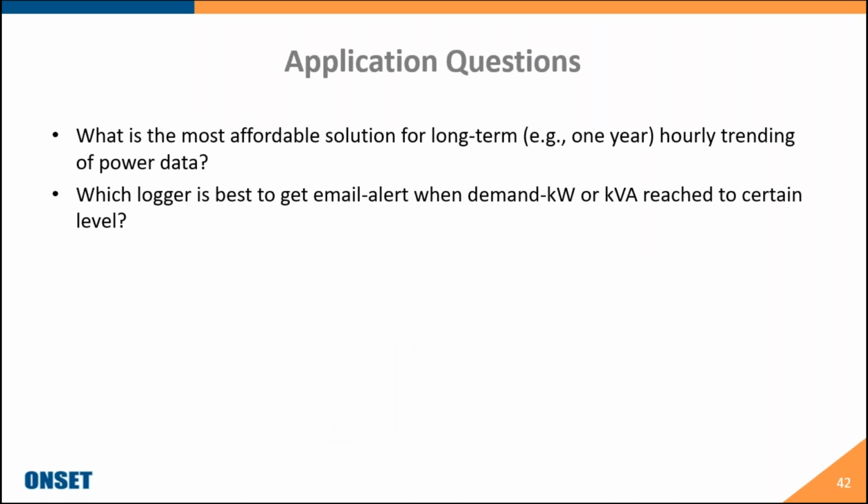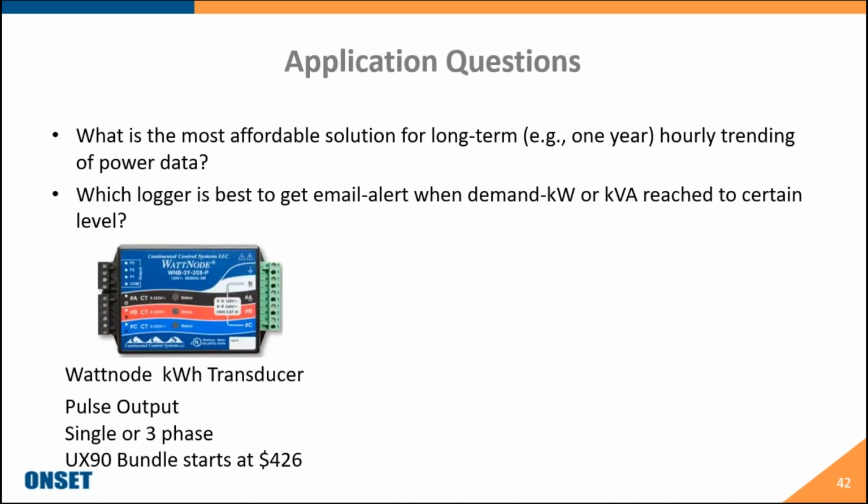All right, and then we had another application regarding monitoring power, and you wanted to know what is the most affordable solution for long-term, 1 year more hourly trending of data logger of power data, as well as which logger is best to get email alerts when demand power, kilowatts, kilowatt hours, kVA reaches a certain threshold. We actually have two options for that.